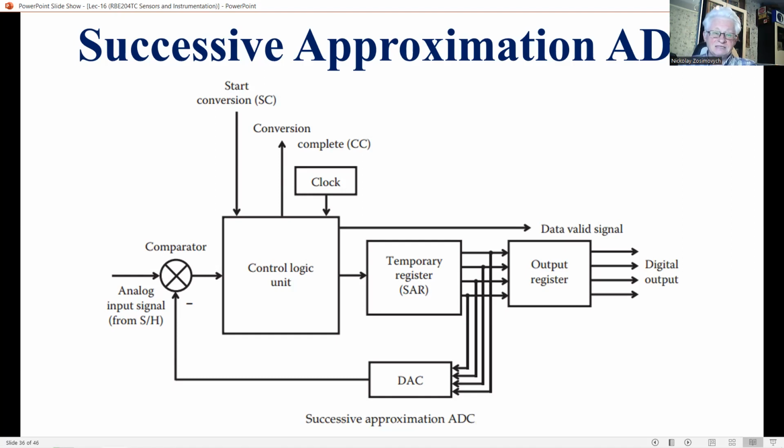And finally, the sign is correctly represented in the digital output. After the conversion, the digital number corresponding to this offset is subtracted from the converted data in the output register to obtain the correct digital output. And then we may assume that the analog input signal is positive.